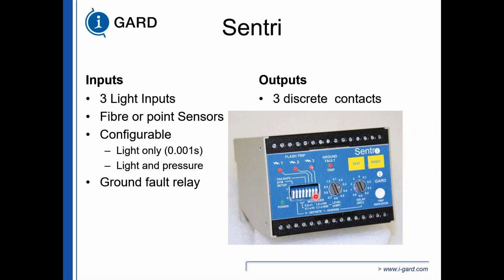So we've replaced all the ground fault relays, the MGFR, 9 models with 1 of these. So you can have multipliers of 0 to 1,000. So you can get ground fault protection from 100 milliamps to 1200 amps with this relay.